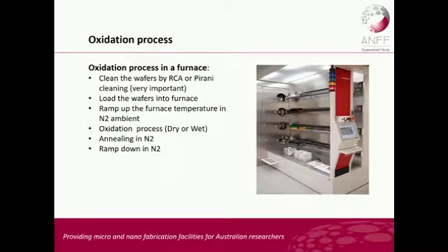So this is a typical horizontal oxidation furnace. One thing that is very important during the oxidation process is cleaning. Before you load the wafer into the furnace, you must clean the wafer properly by RCA or piranha cleaning, which Annie mentioned. This is very important because this will help you remove all the particles, even some defects, which will affect the oxidation process.